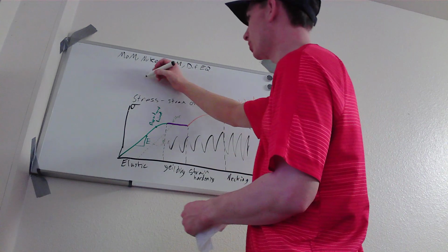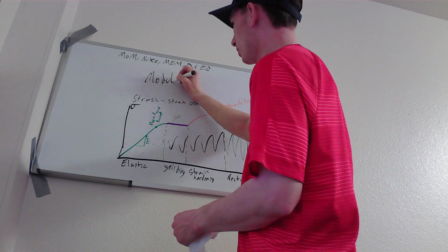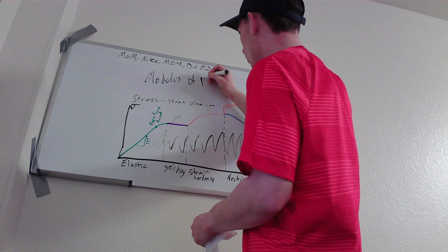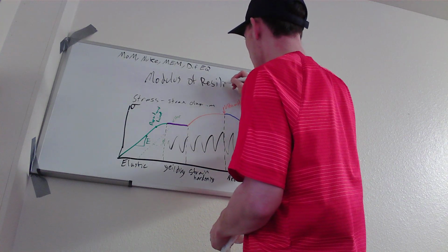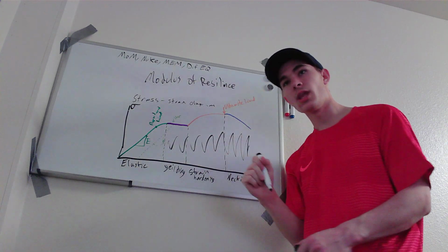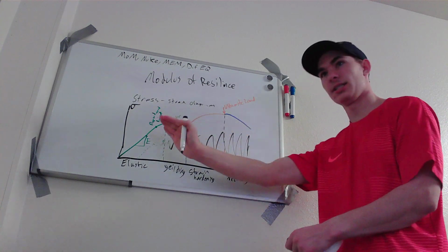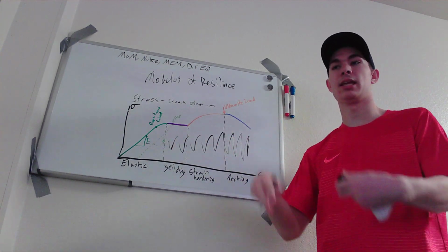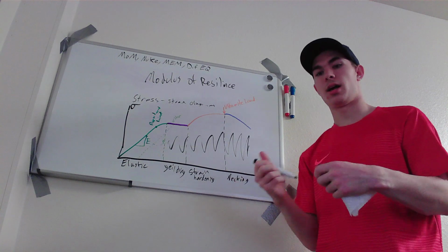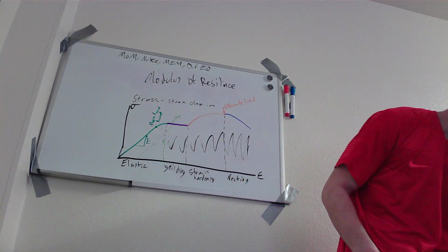That is the modulus of resilience. The modulus of toughness is this entire thing, how much it can sustain before it breaks. Simple, straightforward.